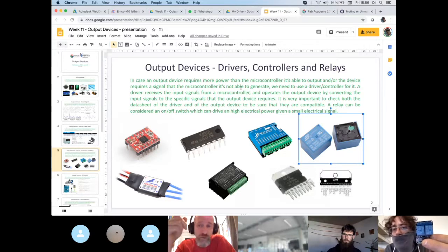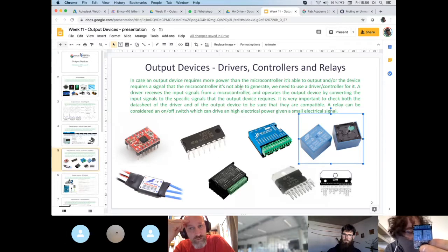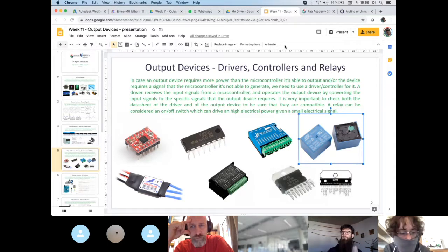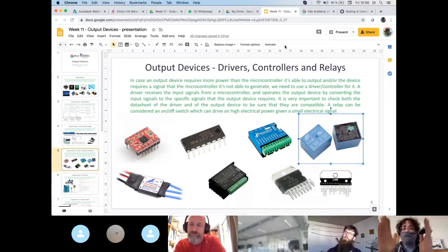Okay. Right. So my question around the solid state ones and the mechanical ones: I understand it's a coil and you just move a switch. There's an actual mechanical switch that moves up or down according to the magnetic coil. Yeah. So there's a complete isolation of the coil voltage from the switched voltage. Yes. Am I right in my understanding that that's not the case in a solid state one, that the two circuits are not completely independent of each other? They are not isolated the same way that you have in the mechanical relay, because in the mechanical relay there is just a space in between.